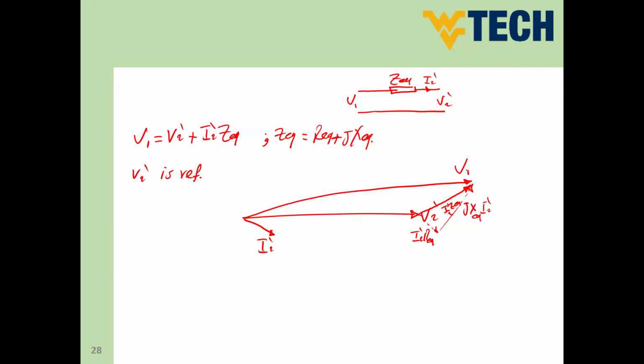In this case, guys, this is going to be the voltage V1. In case of no load and full load, this current would be smaller or higher. In case of no load, we can say V1 equals V2 prime, since no load means open circuit, so we don't have any current.